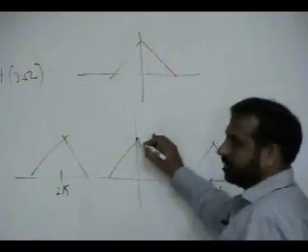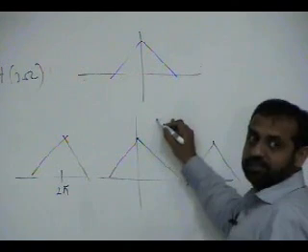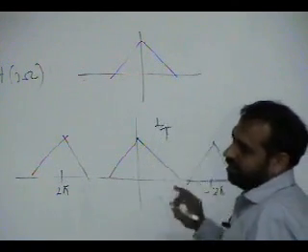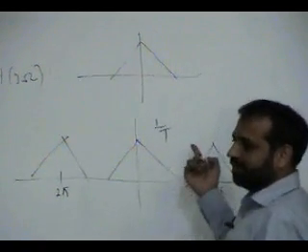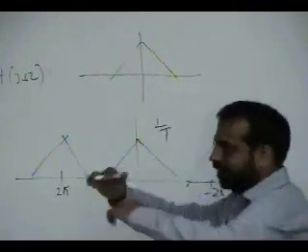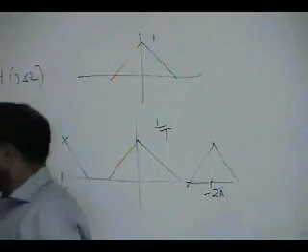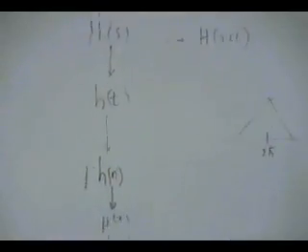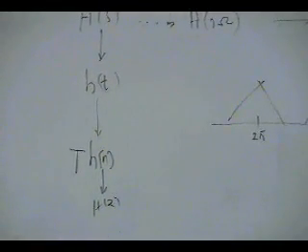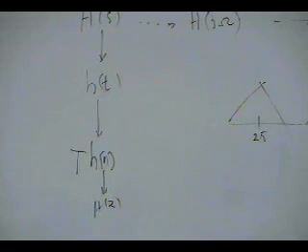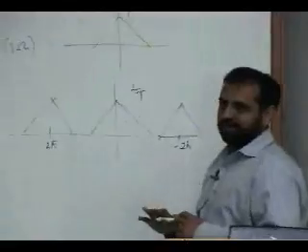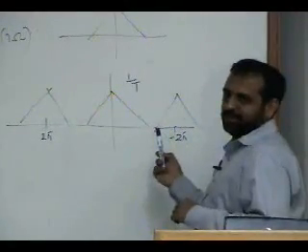But what is the magnitude here? Sampling gives 1 over T. We don't like this. We want it to be 1, because the filter says a 1 here must be 1 here. That is the reason you multiply with T here. A capital T into h of n to make sure that you get 1. So you just scale this: T times h of n.